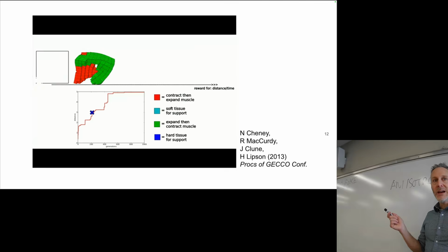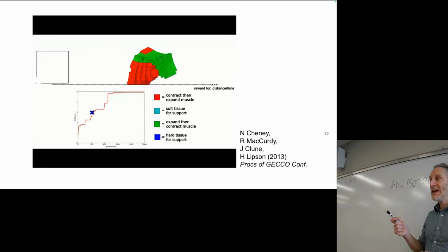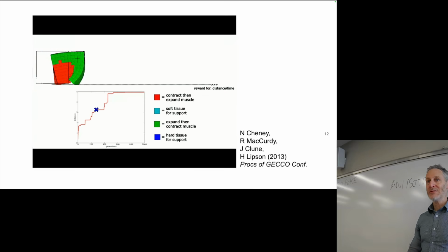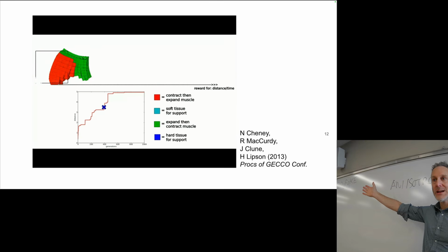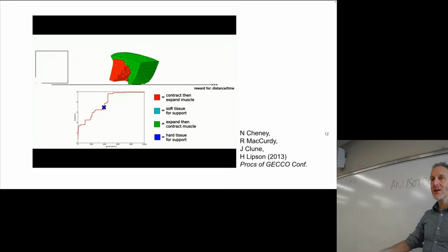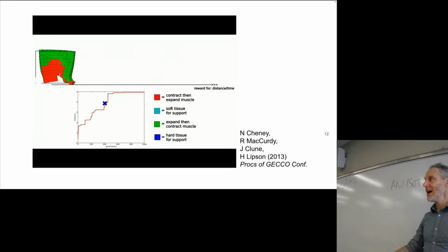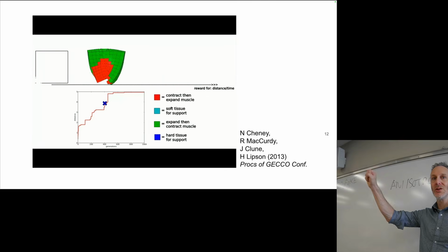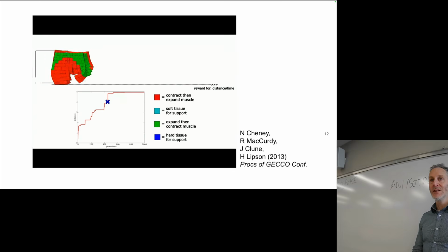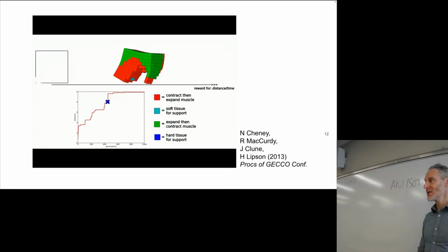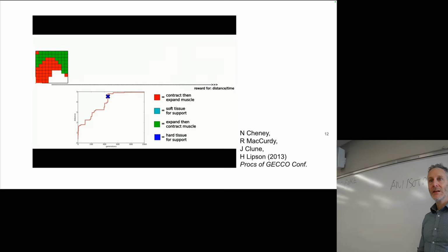Remember that these CPPNs are configured to paint a voxel or not paint a voxel into a particular position, which gives us the three-dimensional shape. And then for all the voxels that were dropped by that CPPN, whenever that CPPN drops a voxel, it also drops some paint or K values onto the beams of that voxel. Everyone got that straight in their head? That's how we're evolving bodies and brains of soft robots.